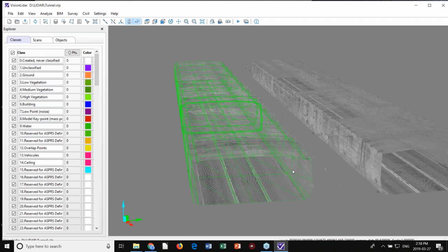And all the lines that we're going to create will be lines with connectivity, which means that every line will be connected with a point that has a point number and a description attached to it. So your drawing can be drawn automatically in your CAD, following your standards.